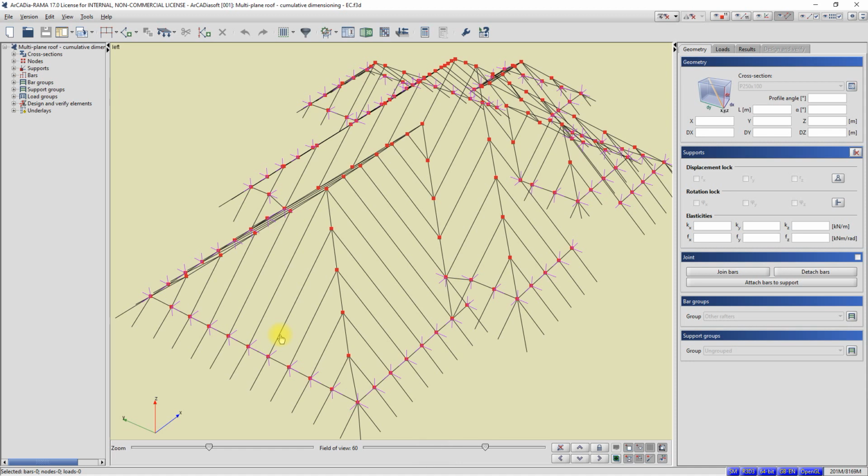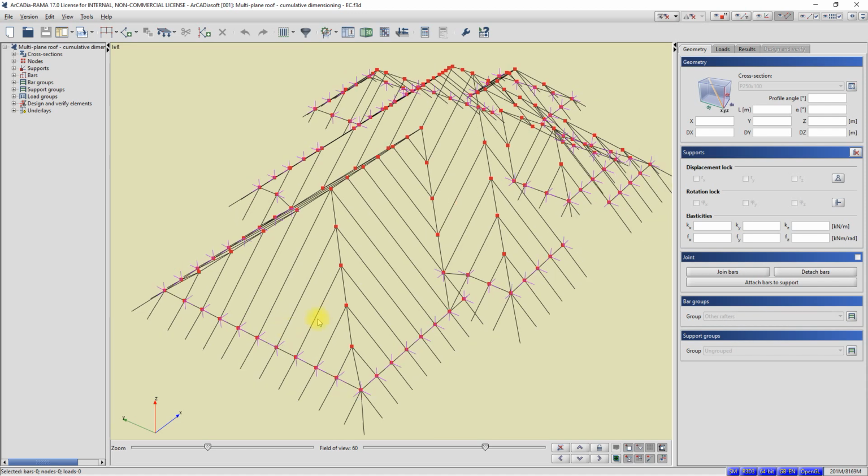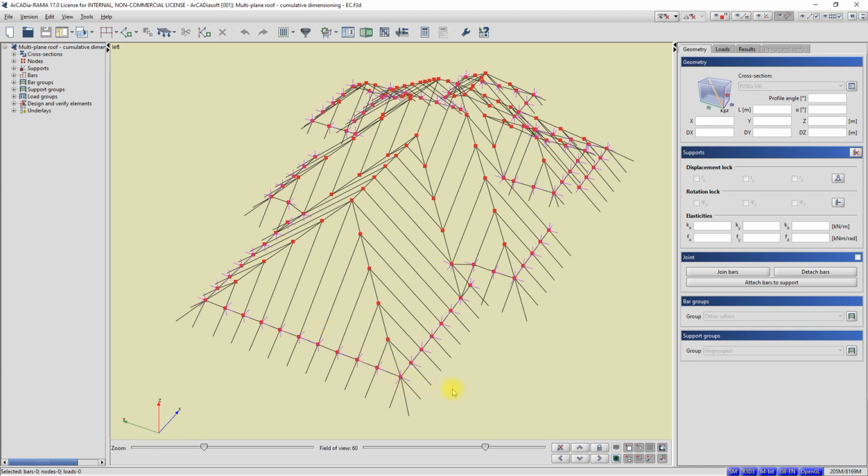We can select multiple objects at the same time. We can do this by defining the rectangular area of the window. To start selecting from the window, press the Control key and indicate with the left mouse button a point in the workspace. I indicated a point, which is the first corner of the rectangular area of the window. Next, I need to indicate the opposite corner of the window.